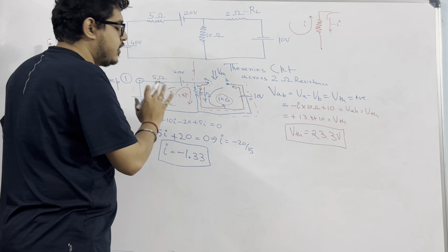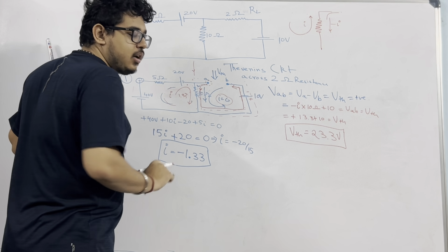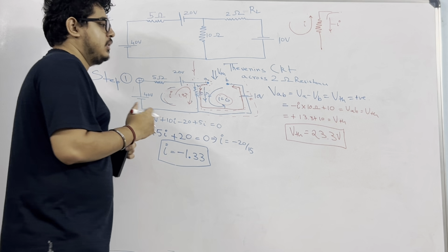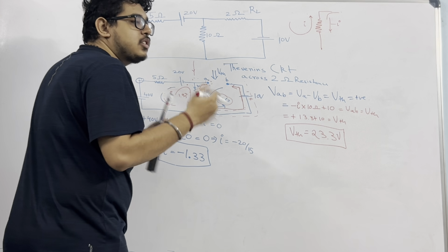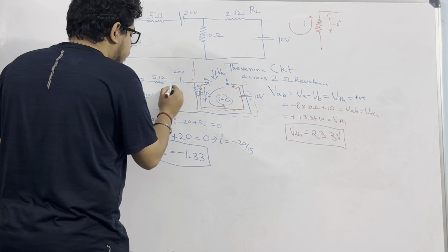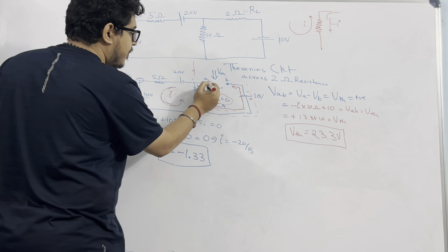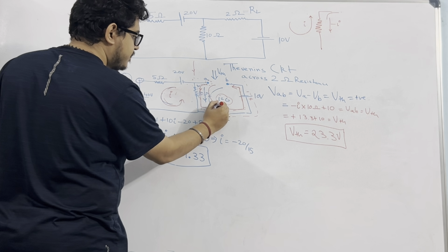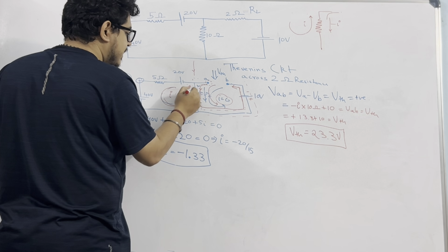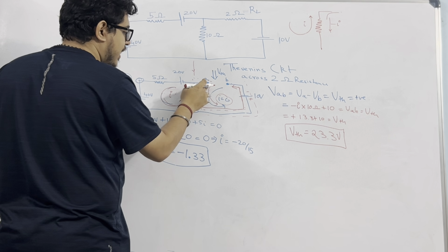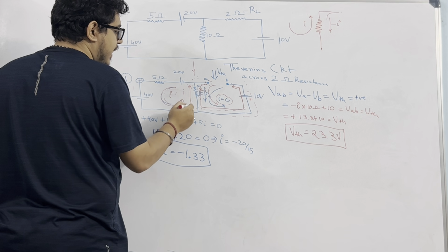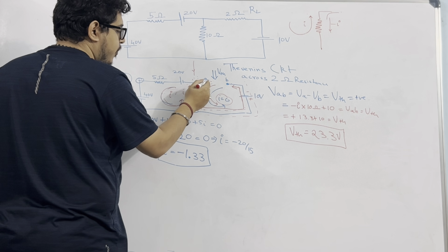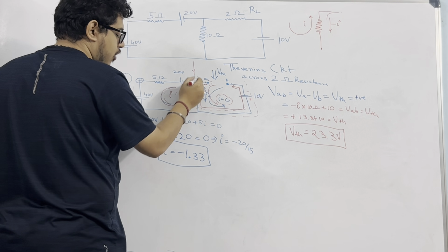That's it. So you have to be very strong at sign conventions if you want to be very good at the analysis of electric circuits. Otherwise, whatever you assume, you just keep on following that. What I assume, current to be like this, I am coming from this now like this. If I is flowing like this and no current is here, and I go from top to bottom, then I have to write minus I, because I assumed I to be like this. So if I want to write a potential drop from A to B and I come up to down, it will be minus I.